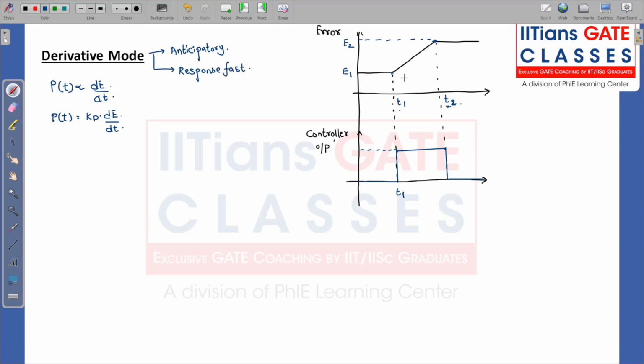Now you might be wondering, if this is so good that we can predict the error and the controller can take action, why don't we use it always? So there is a problem with derivative mode. Suppose my error looks like this. What will happen if I take the derivative of this? For a constant, this is basically a step signal. So there will be just a simple impulse at these 2 points.